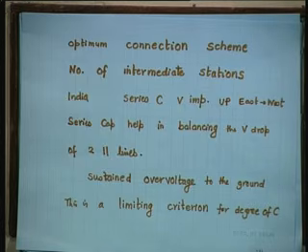Also resonance, subsynchronous resonance, especially SSR, which is again a PhD topic. Many PhDs have been produced on SSR, which is a very important phenomenon that can be produced because of series capacitance. So, series capacitance is a good medicine, but there are side effects, and one of the most important side effects is SSR.